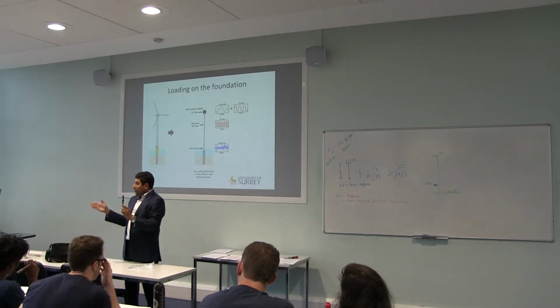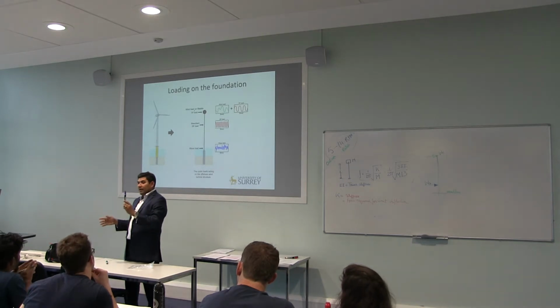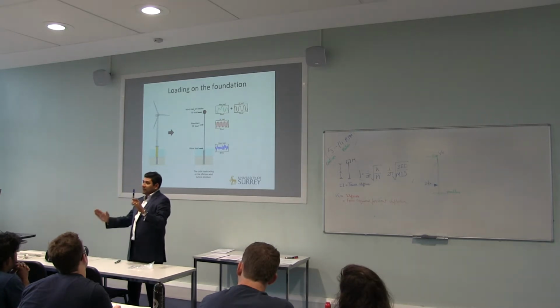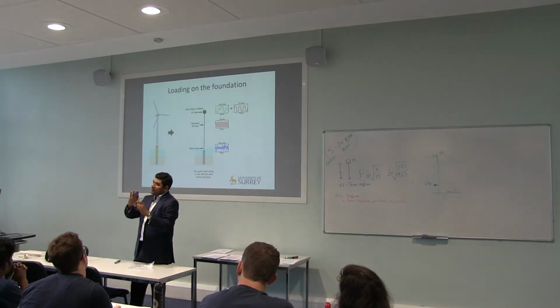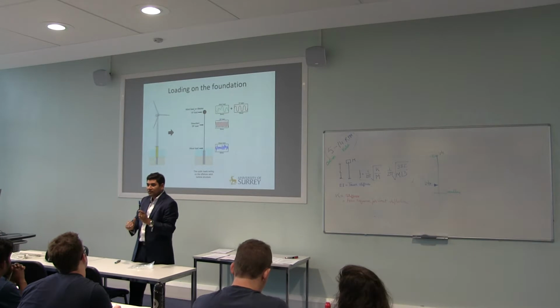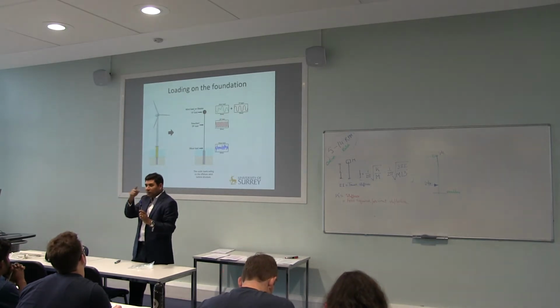The load on the tower would be, when the blades are not in front, you get the full load on the tower. But when the blade comes in front, what do you see? Shadowing. So the tower will experience a big load and a small load. As soon as the blade passes the tower, there is a drop in the load, and that would be 3 times the RPM.